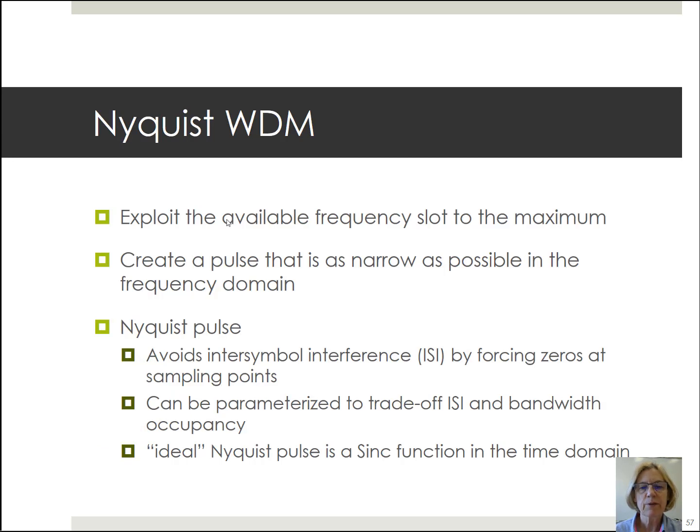So let's begin with Nyquist WDM. The idea is to exploit the available frequency slot to the maximum extent possible. And in order to do that, we have to create a pulse in the time domain whose spectrum in the frequency domain stays as narrow as possible. Now, the problem of pulse shaping to achieve various goals has been solved by Nyquist, and of course this is the origin of the name of Nyquist WDM.